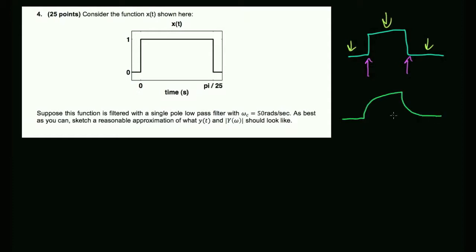The only thing that makes a difference is the time constant, right? So here I've set a cutoff frequency of 50 rads per second. The only thing that would change if I change the cutoff frequency would be how quickly it rolls off. And actually, we've talked about that as well, haven't we? We did a demo on that. We didn't really get into a lot of specifics about how to calculate the cutoff frequency and how that corner is affected and time constants and so on. But we've discussed it in broad terms. From a frequency perspective, what would happen?